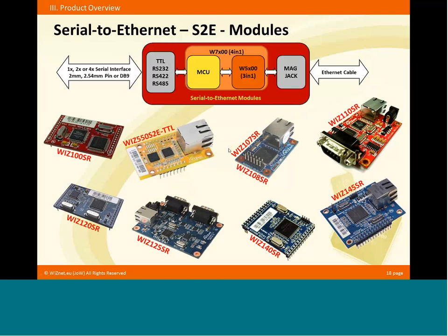What we want to show you today is using these serial to Ethernet modules having TTL level outputs on the pins, and we have a baseboard that converts those to RS-232 or to RS-485. Also we have those applications for all the other modules, and we use all kinds of MCUs. We have here an 8051 from Core River on this module. We have here our own 8051 core. Here we use the NXP Cortex M0.